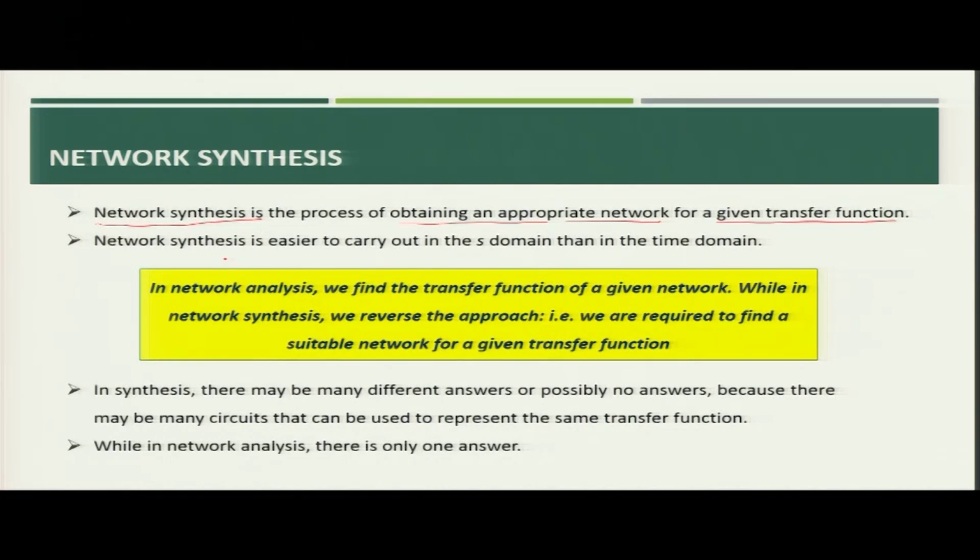Now, this network synthesis is just opposite to our network analysis, where we get the circuit and we try to find out the transfer function of the given circuit. So, network synthesis is easier to carry out in S domain than in the time domain. When we differentiate between network synthesis and network analysis, we can say that in network analysis we find the transfer function of a given network, while in case of network synthesis we reverse the approach. That means, we are required to find a suitable network for a given transfer function.